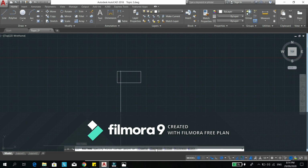For the elevation, it's the height of your rectangle. This is already used for 3D or isometric drawing, same as with the thickness. But with thickness, you can extrude it. In 3D, you can put a height, or you can pull the height of the rectangle once you choose the thickness.